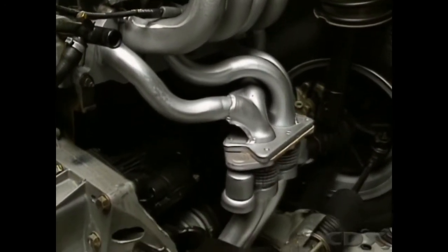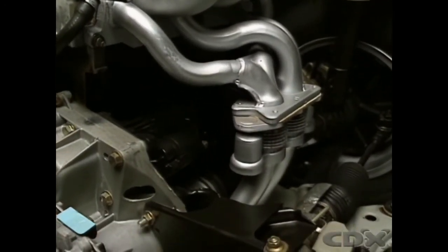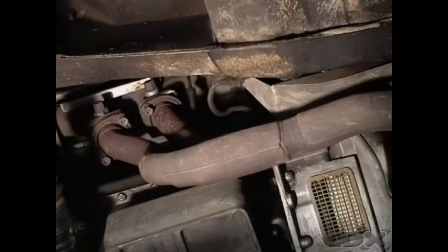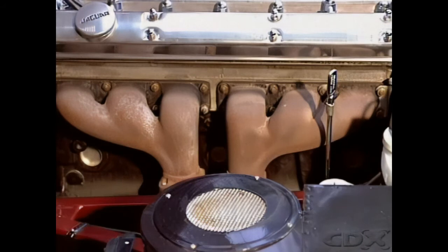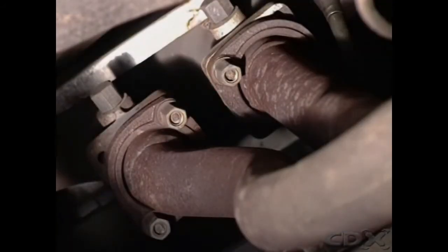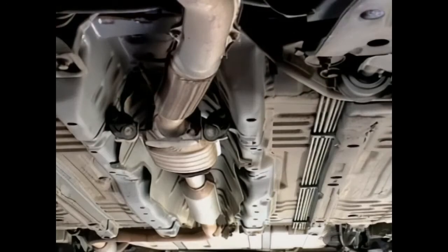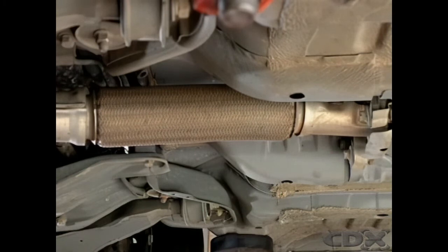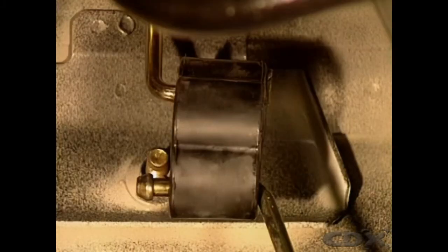The engine pipe is attached to the outlet of the exhaust manifold. It can be designed to branch in various ways. On this engine, the exhaust gas from 3 cylinders is fed into each engine pipe. The system needs flexible mountings and sometimes flexible joints to allow for engine movement and prevent noise and vibration being transmitted into the vehicle body.